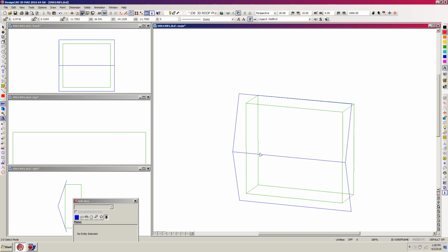So now I need to take care of my gable ends because this is a truss roof, and normally trusses have what they call a 1/4-inch butt cut. It's just on the outside of the plate line. What the butt cut does is keep the bottom quarter of the truss from coming to a very sharp point where it interfaces with the upper quarter of the truss. It's kind of hard for them to make those feather out nicely, so they just put a 1/4-inch butt cut on them. So what I'm going to do is select the walls again.